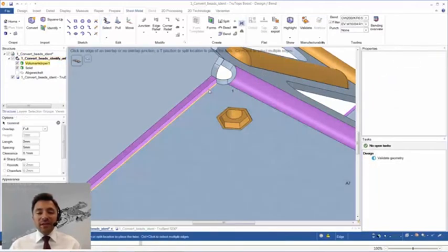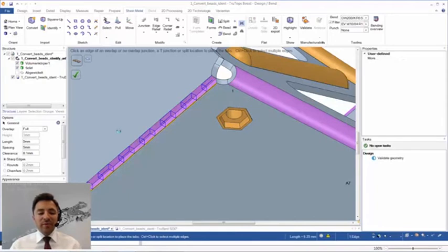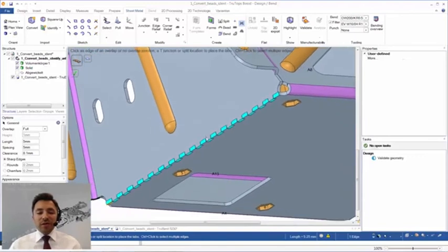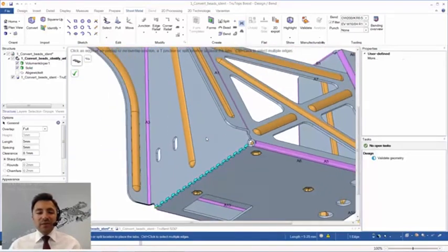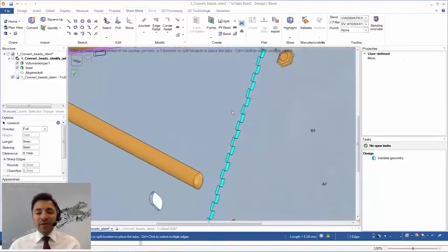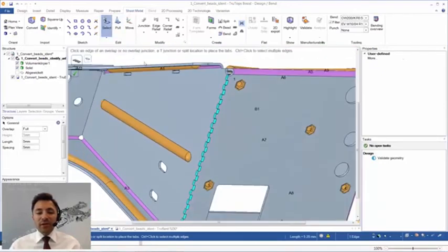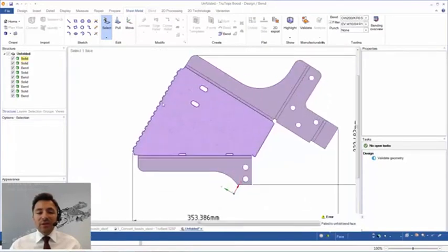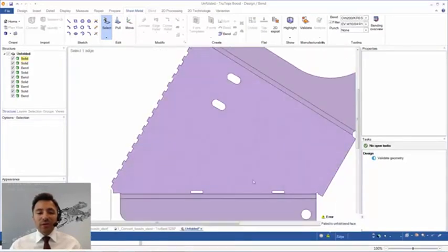So if I activate the tab tool, I need to select an edge, and you see there's a preview. There are some geometry dimension settings, and I'm happy with the default values and just click the check mark. So in that case, you would probably produce the part cheaper. It's out of 3 parts, and that would be one possibility of doing that. So if I select that face, click on Unfold, you see immediately how the part would look like within the tab region.